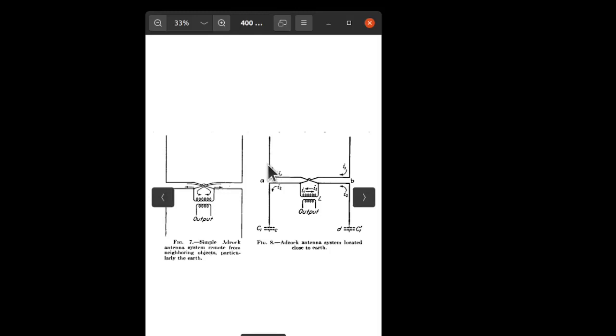Now, each of these points can be abstracted into four separate and isolated monopoles arranged into a square pattern, much like you see at these points. And think of these elements being driven against ground through a transmission line that feeds ground at this point and feeds the elevated vertical at this point. We'll say that this is ground, and this is specifically talking about ground with this capacitance down here. We'll see more of this coming up.